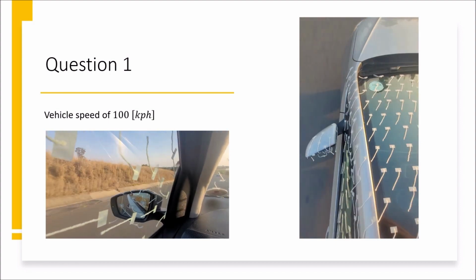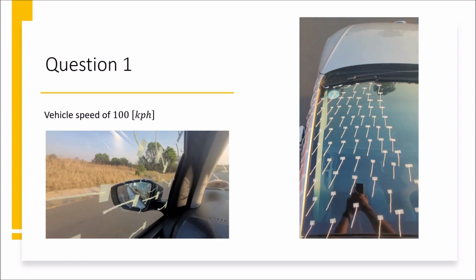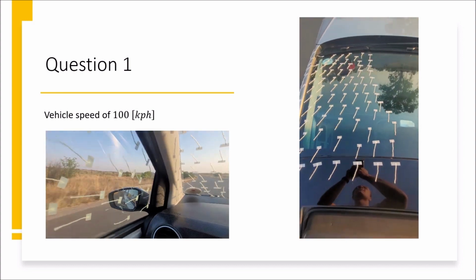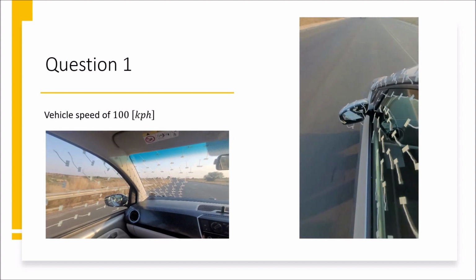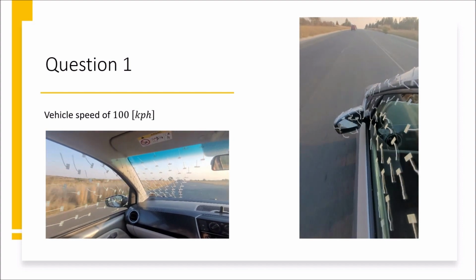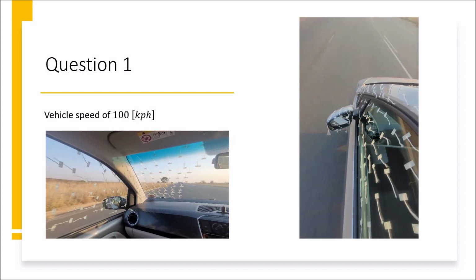As the flow moves over the A-pillar, the airflow separates at the sharply defined lines on the A-pillar. This can be seen due to the tufts on the A-pillar that are close to the windshield not moving very much, and the tufts on the A-pillar furthest away from the windshield moving radically in different directions.